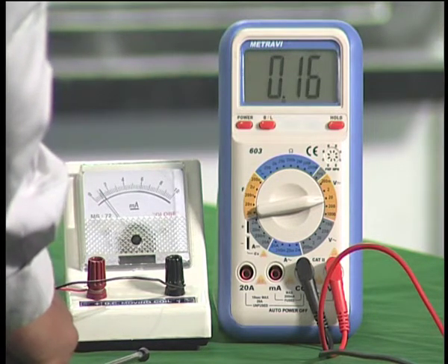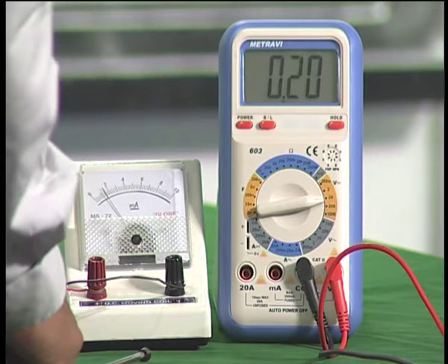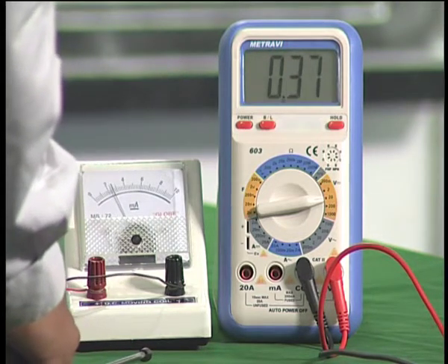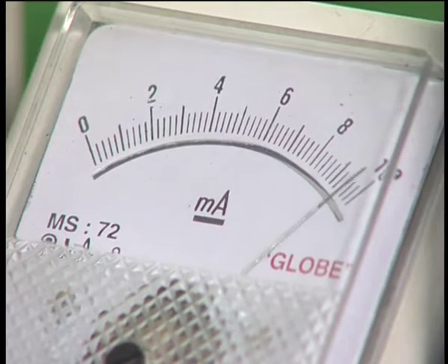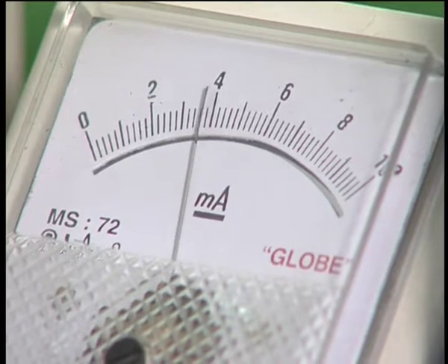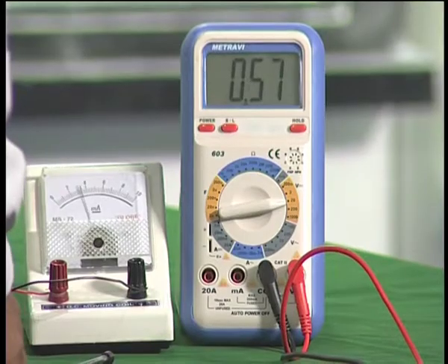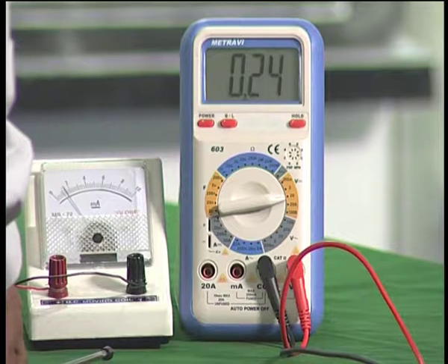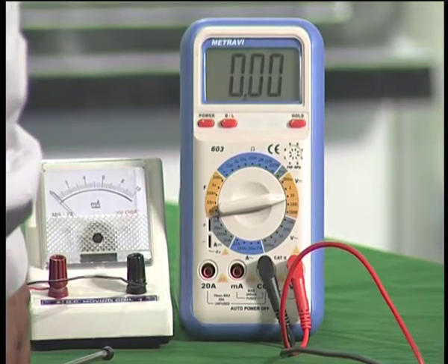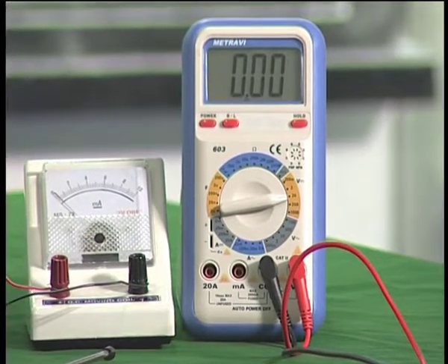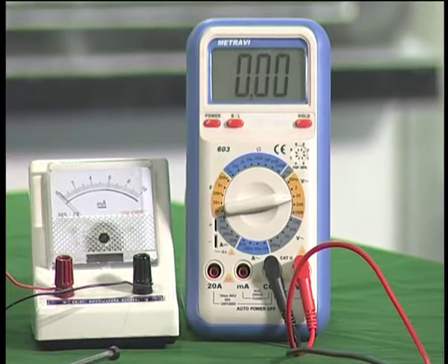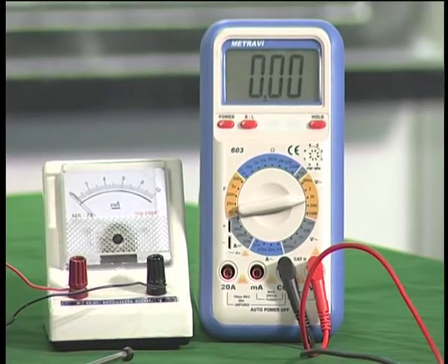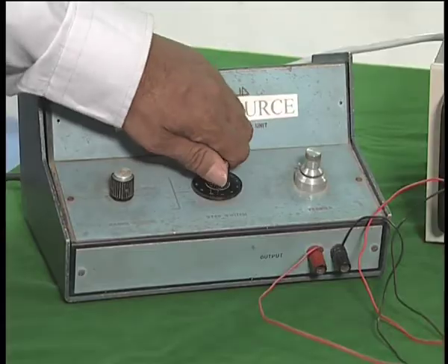You see it is about 1 milliampere, now it is 2 milliamperes, and as I keep on increasing you find it is 4 milliamperes, 5 milliamperes, and it keeps on increasing and it goes beyond 10 milliamperes. That means the IDSS is going to be larger than 10 milliamperes. That is what I see here. If I use much larger, maybe 50 milliamperes, I may be able to get about 12 or 15 milliamperes as the IDSS.